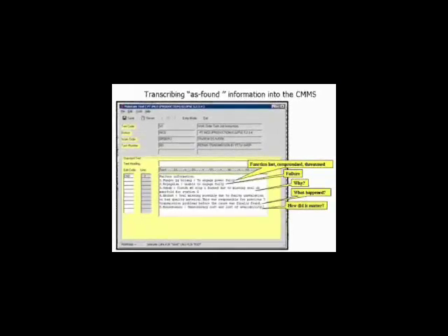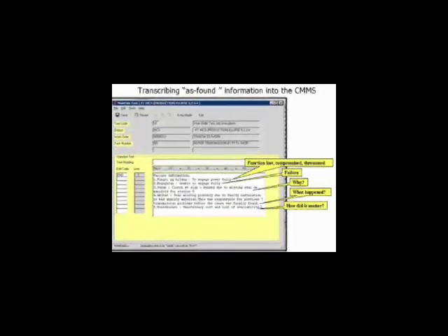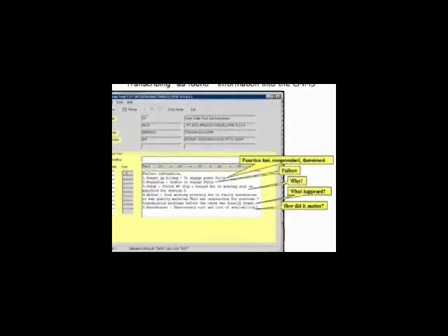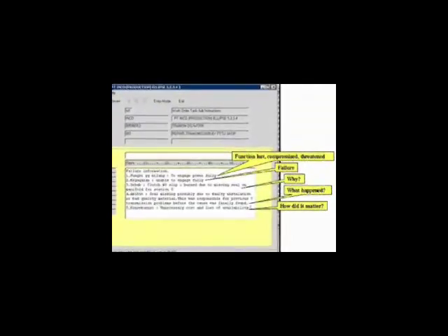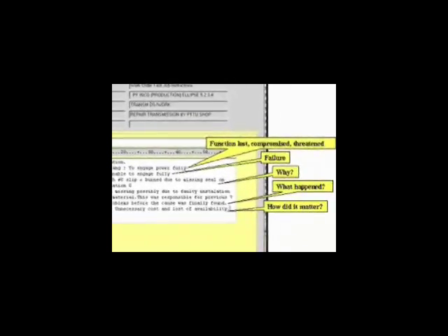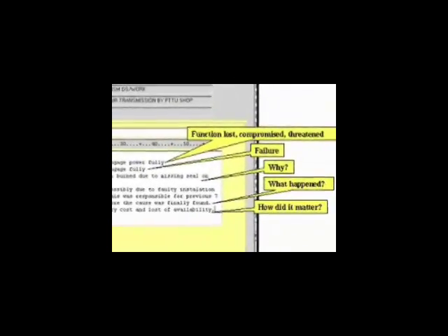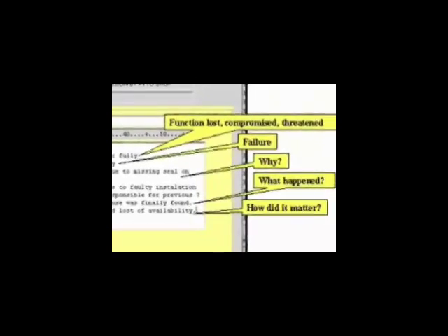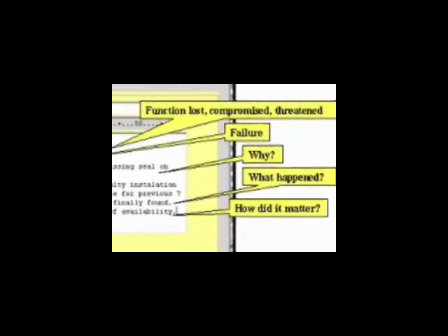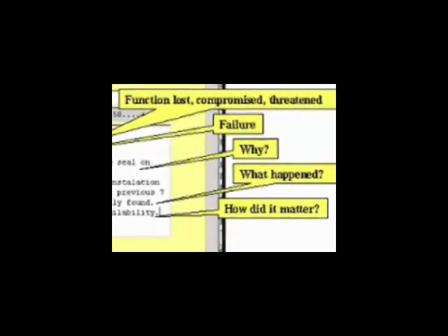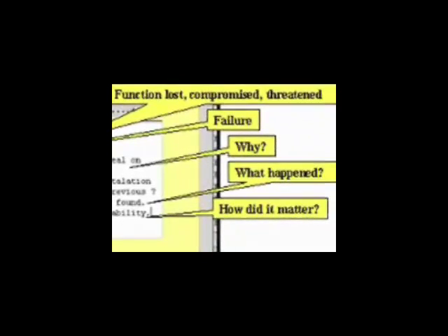How should we record this information in our CMMS in order that it can be analyzed and used in a predictive data interpretation model? The secret to a continuously improving CBM program is good recorded information. In maintenance, we must capture the 5 reliability-centered knowledge elements each time a work order is closed.